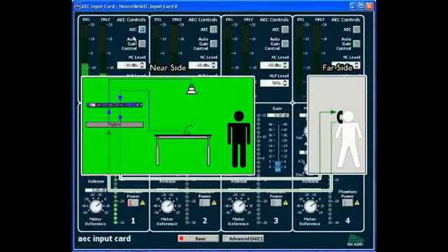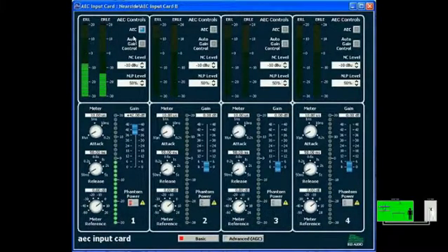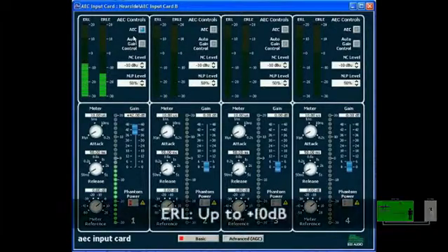Okay, now let's talk about ERLE a bit more. Traditionally, AEC algorithms are incapable of removing echo from the signal path once the ERLE surpasses 0. But BSS Audio's uniquely powerful frequency-based algorithm allows for full operation at up to +10 ERLE levels, an industry first.